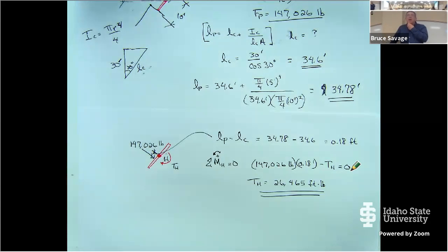And I would say that in canals, the sluice gate is more operational too, because you create the smallest area when you're going vertical versus if you're trying to do incline. And the vertical actually only creates a pressure force rather than weight force. And there are operational issues if you try to do it at an angle. So yeah, they're kind of related, but not entirely.